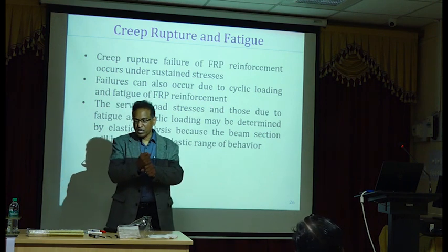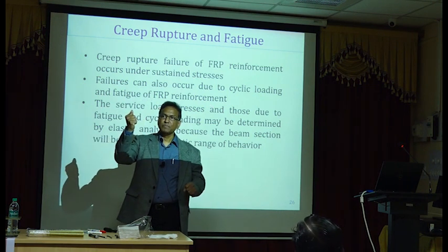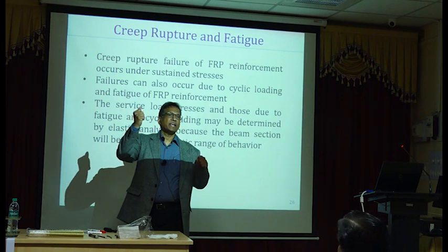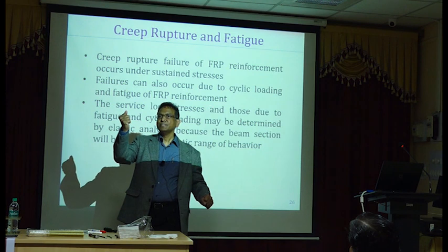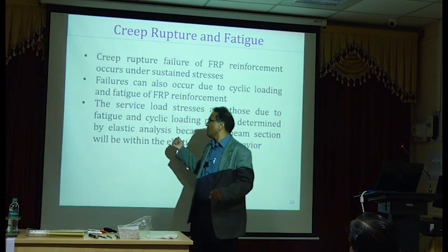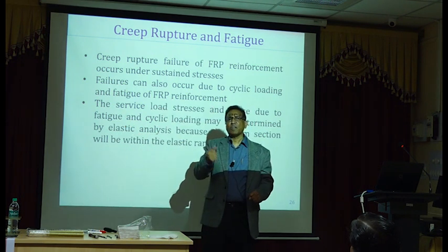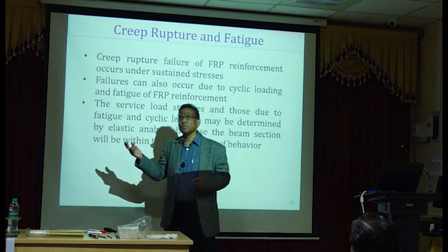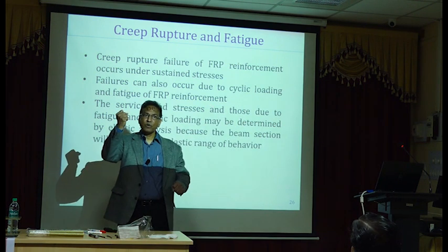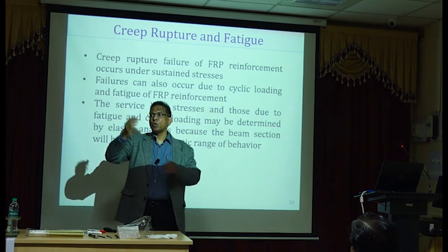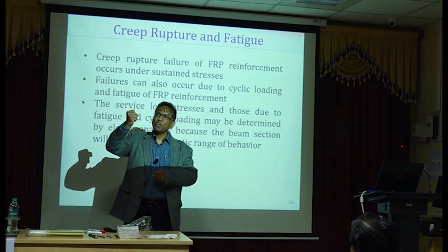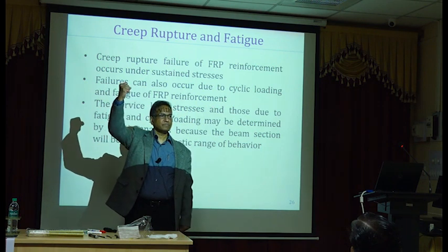If I apply a load on an FRP bar and maintain that load for a very, very long time, the failure will happen all of a sudden. Suddenly it will fail because of the sustained load. That failure load will be much smaller than the load at which we fail by static loading.